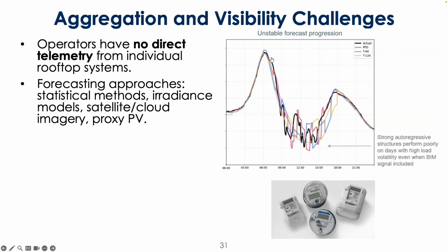And their 2 hour, 1 hour, and then RTD, which is the 15-minute, right, all kind of get it not very accurately. And that's because the variation from things like weather and cloud cover is very hard to accurately predict. And when you have a lot of solar resources, you get stuff like this happening. Yeah. So is that the reason for the load being so variable? Yes, exactly. Because this is going to be net load. Yeah. Gotcha.